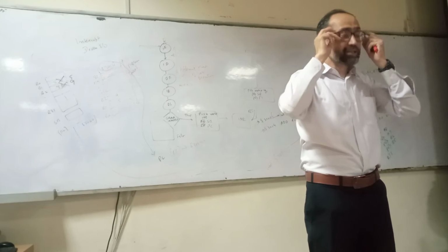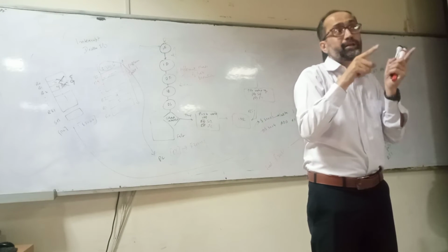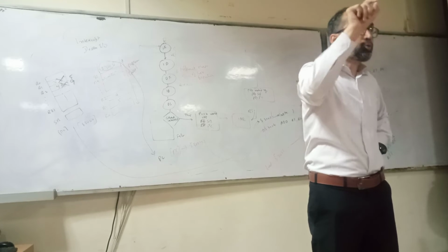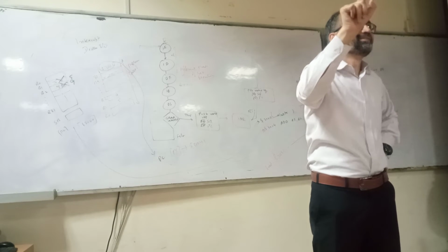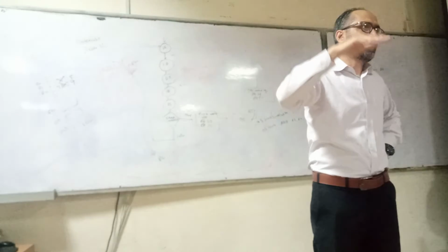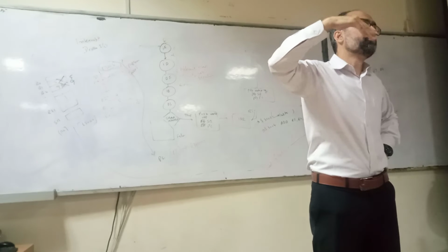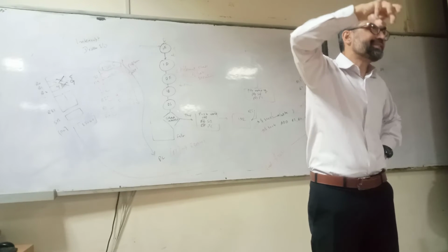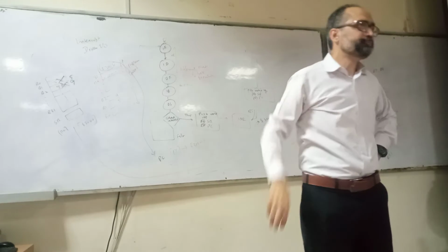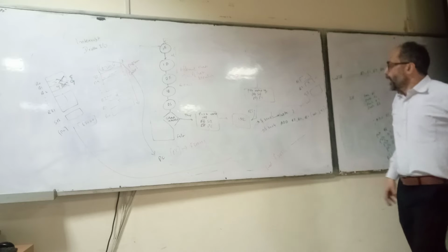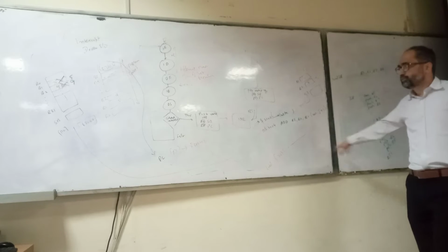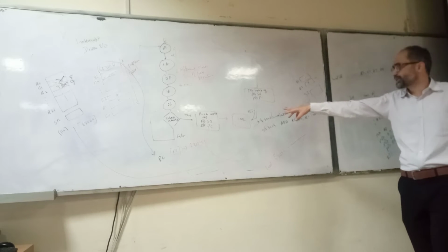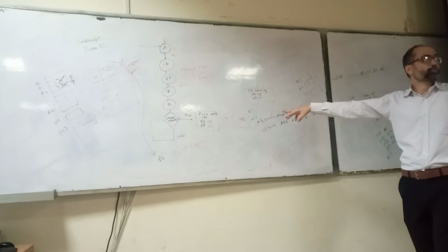Okay, if the microprocessor is interrupted during a sequential instruction, then the value of the program counter it will push on the stack will be the address of the next instruction. Okay? And before jumping to the subroutine, we push all of the working registers on the stack, then the status register, and then also the program counter.